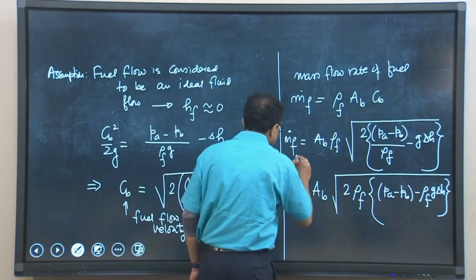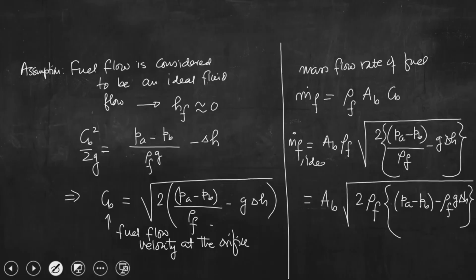So, let me write here, this mass flow rate is the ideal, right, and that means our analysis, that is the ideal fluid flow, will deviate in real practice accounting for these factors, that is the specific gravity of the fuel, surface tension effect as well as frictional losses, and hence the mass flow rate of fuel obtained here is the ideal mass flow rate.